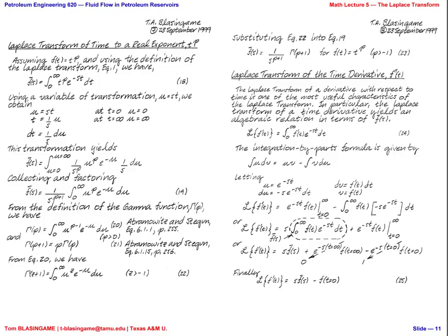So the diffusivity equation for linear flow, you'll see, sorry, this is P: the second derivative of P with respect to xD is equal to dP/dt, right? You may know it as the heat equation, as the diffusion equation. In this case, it is the diffusivity equation for linear flow.